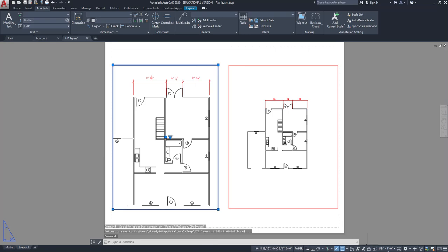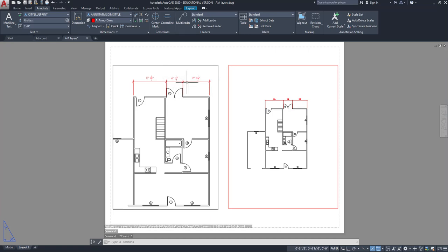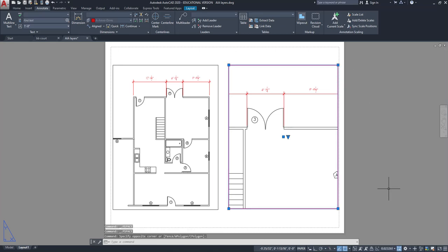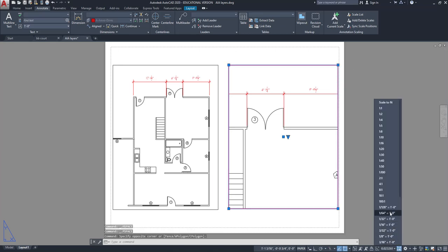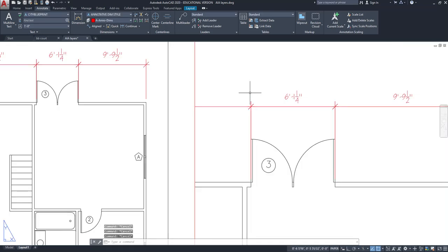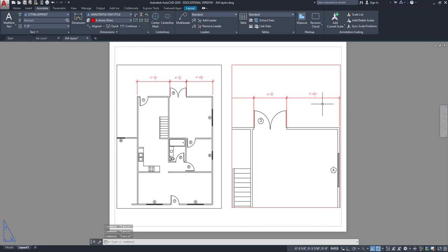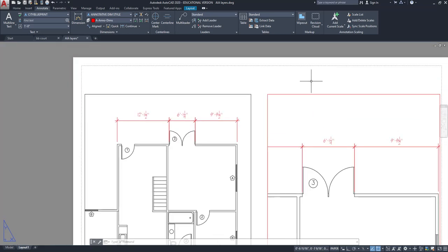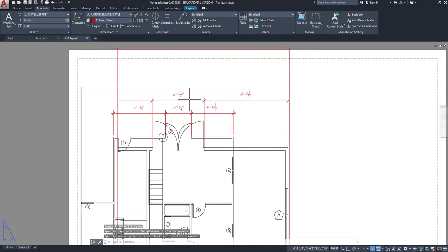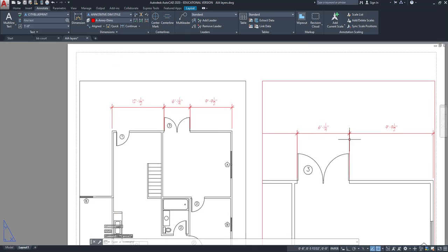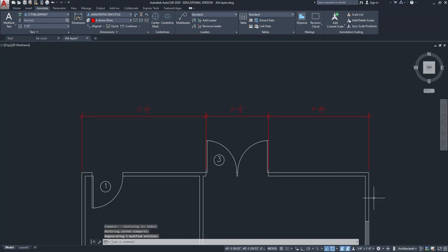At 1/8 of an inch scale, this viewport is scaled to 1/8 of an inch. This looks wonderful. I'm going to double click here, zoom into this, double click out, select. I'm going to change this to 1/4 of an inch. Okay. And now at 1/4 of an inch, that looks lovely as well, okay? So right now, these two, I'm going to move this over here real quick. Do you see how if I put them right next to each other, the text is the same height, right?